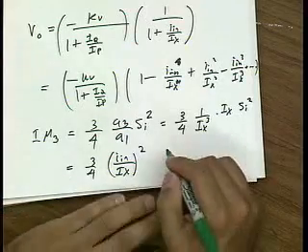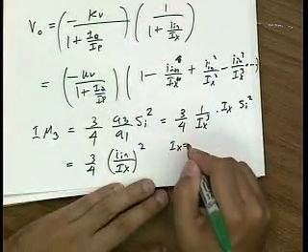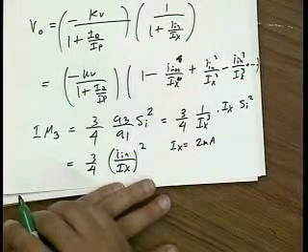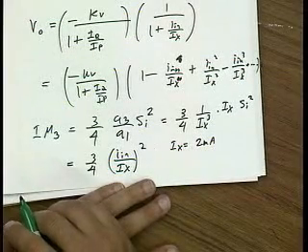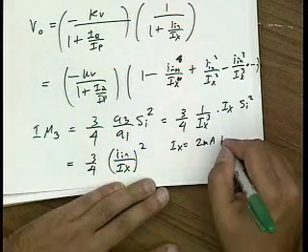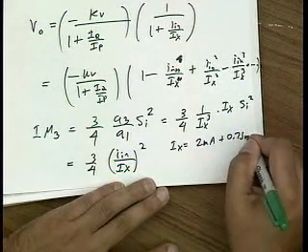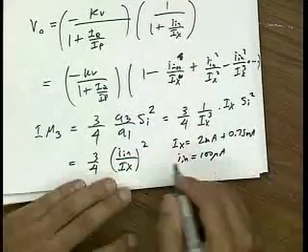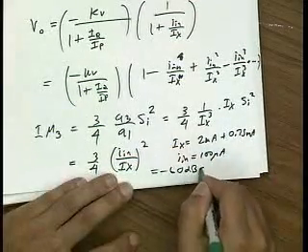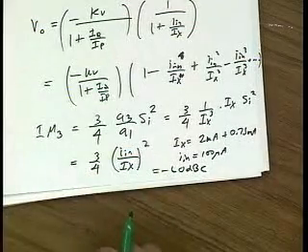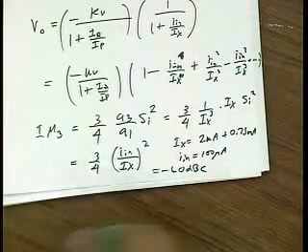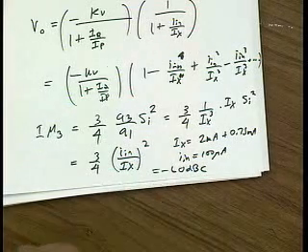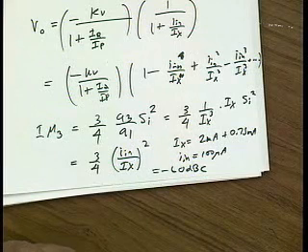Okay, and then just to finish this off, I'm given that if I go through and plug in numbers, I find that Ix is 2 milliamps plus 3/4 of a milliamp, and my input is 100 microamps. So this gives me minus 60 dBc. All right. This is dB carrier, so it's a ratio of the input signal to the carrier, the fundamental.